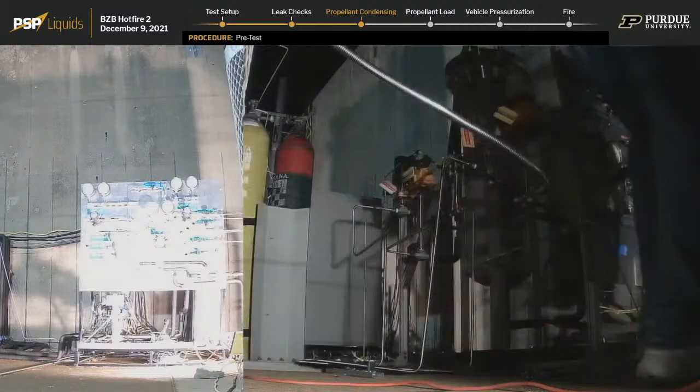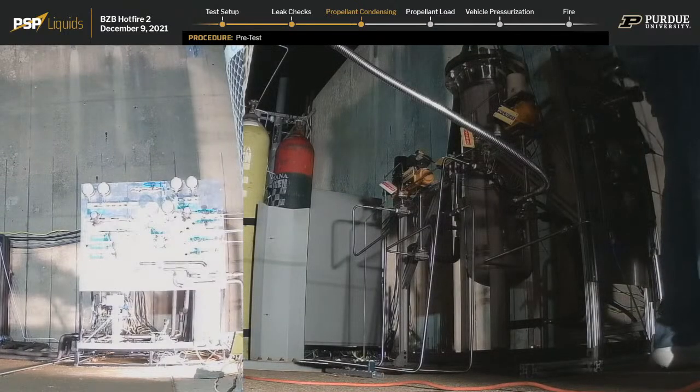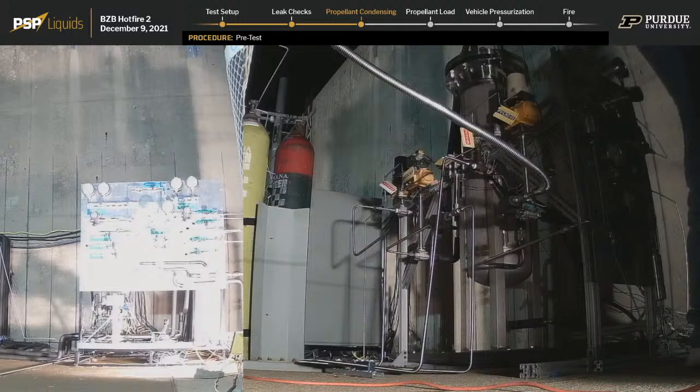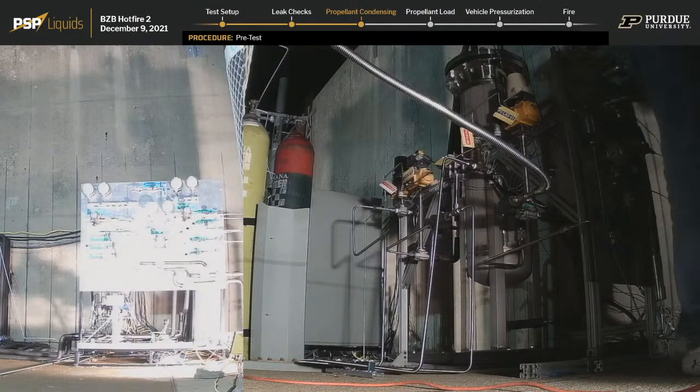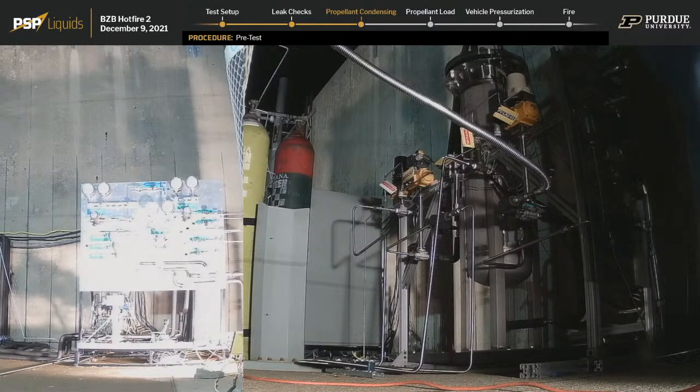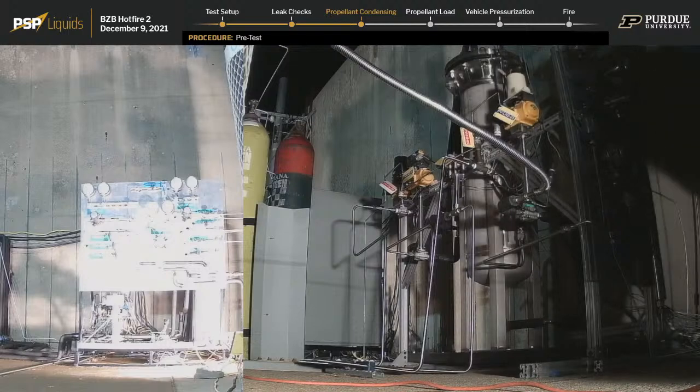We want to make sure we're capturing all context, including critical relief valves. Now, have you heard a relief valve actuate before? Yeah, they're quite loud. So when you hear relief valves actuating on stream, you'll probably hear a pop and a hiss after that. And you might hear that repeat. And that's a very normal thing when our system's being filled. So, that's an excellent question.